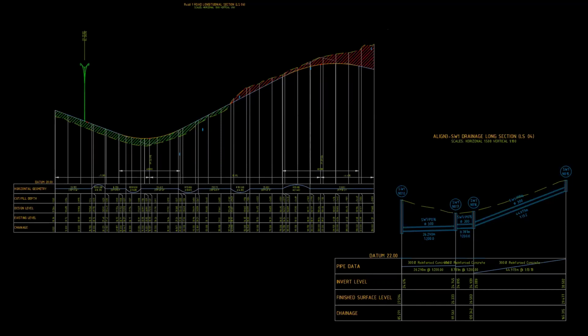You then can create things called a profile view, which is a way to view that information in a graph where the x-axis is your alignment geometry in terms of length, and the y-axis is your elevation. Then the view can be enhanced, so you can start to design profiles over the top. That's what we'll call a design profile or a vertical grading.